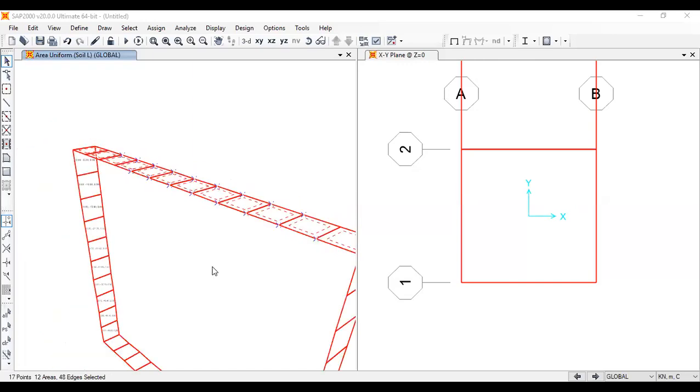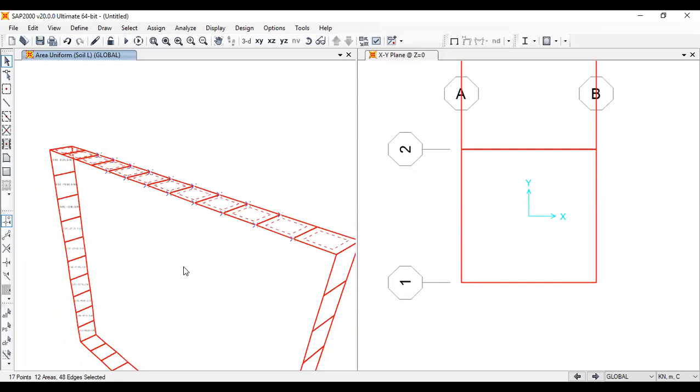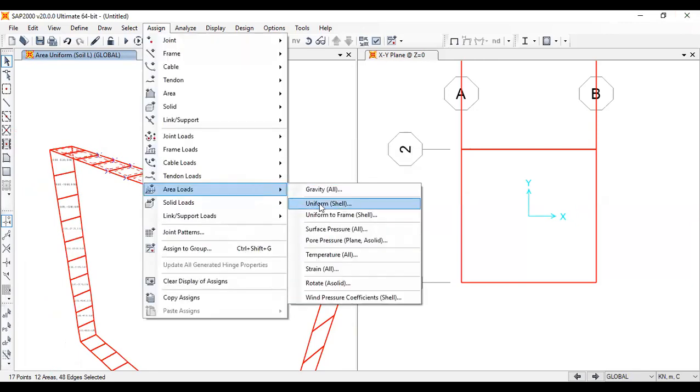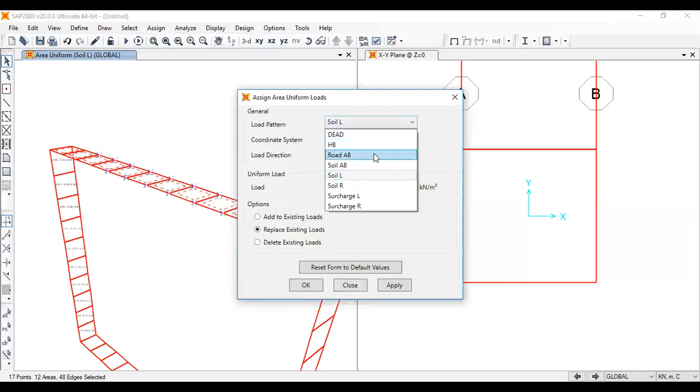When I select this element, the density of the selected soil was around 17.6. So I have 0.8 thickness, so 17.6 times 0.8 means around 14. So I'll apply that pressure. So that is soil above.